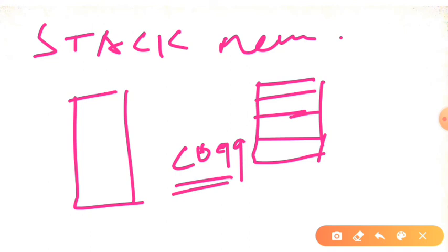This address we need to store in the stack pointer in order to tell that this is the starting address of our stack. Now you know that when we store something in the stack, we store it one by one, and when we retrieve something from the stack, we can retrieve only the last thing we have stored. So it's like a last in first out kind of stack.